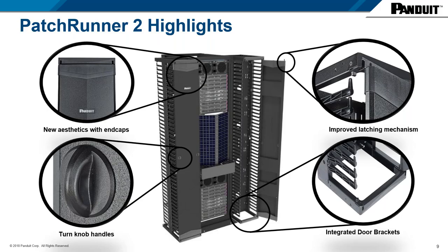And what we did with this is we made it much less force required to get that latch to secure that hinge pin, both at the top and the bottom. So what that means is you just need less force to close the door and make sure that it's fully secured and closed. That's going to reduce the risk of any door falling off out in the field, and it makes it much easier to use.